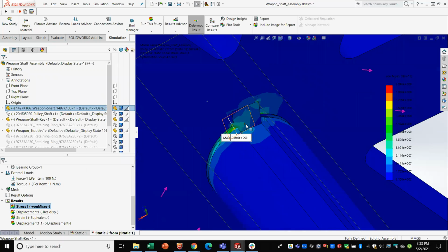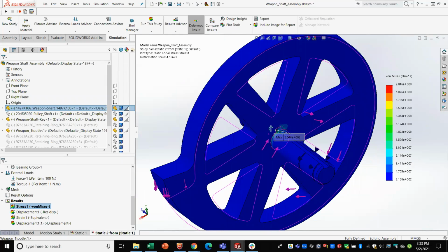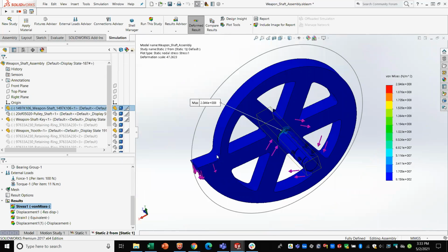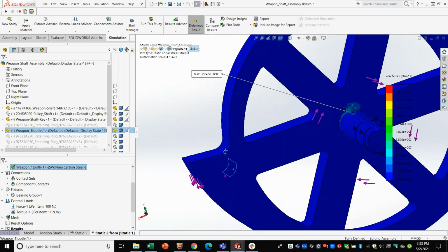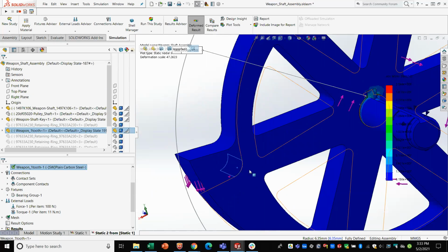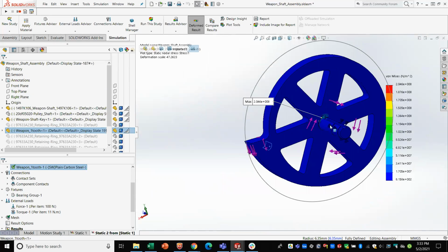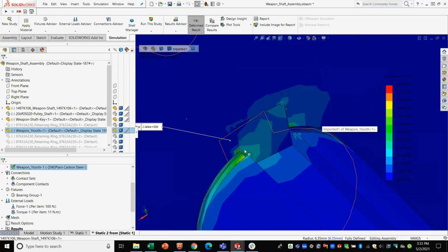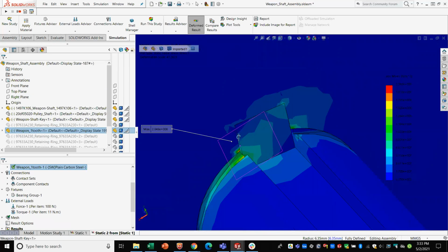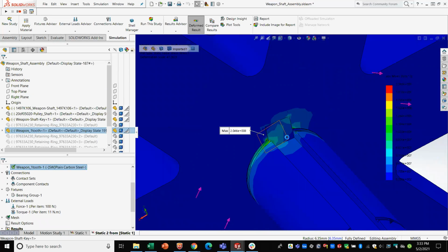But you can see that now, the stresses in this fillet didn't change. The stresses in this fillet should theoretically be pretty similar to what they were in the last model, but it's showing as blue because now the stresses in the area around the keyway are so much higher that that's what gets the red.